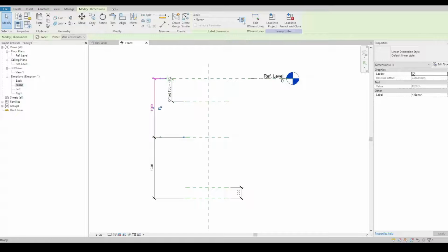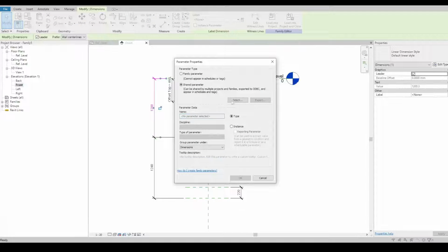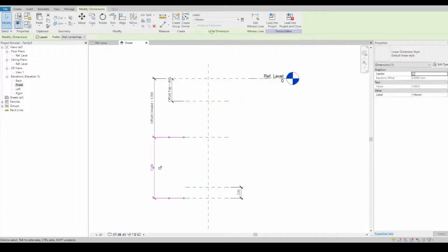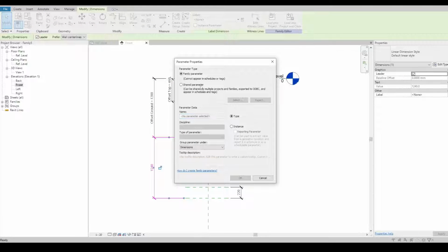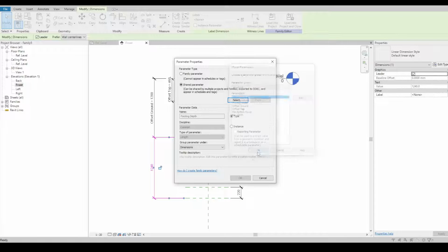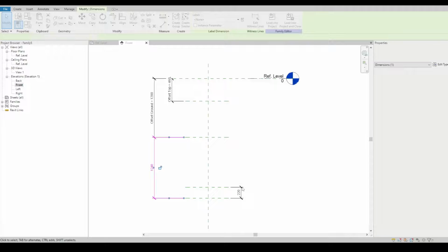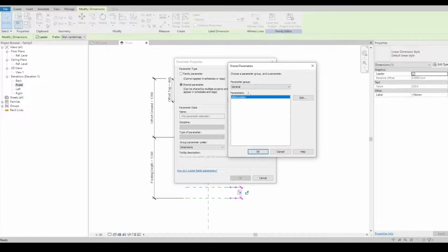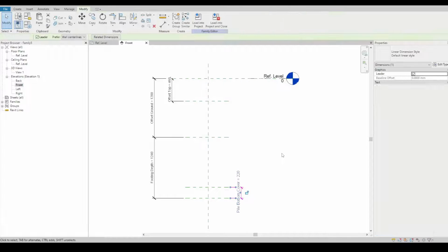We're using shared parameters so that on successive families that we make up, we can swap them in and out inside Revit, and these values will stay the same. If we don't have them, the families will start to jump around. Okay, more shared parameters. This one's pile bottom cover.